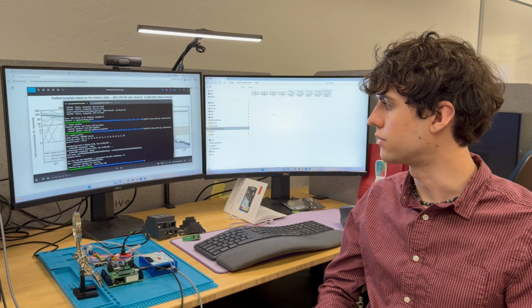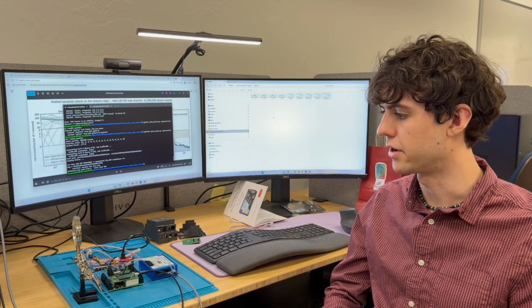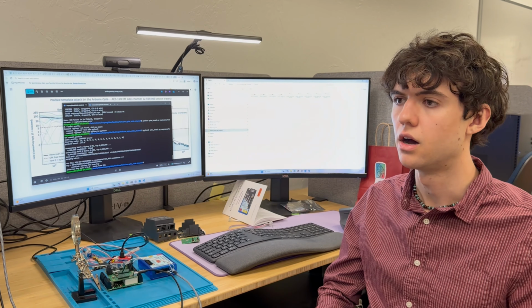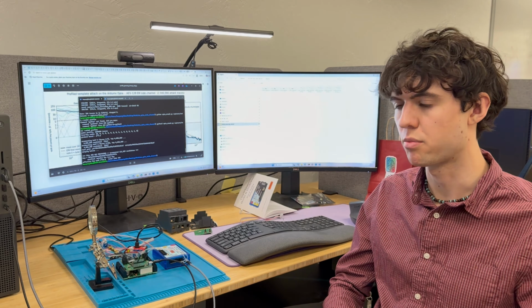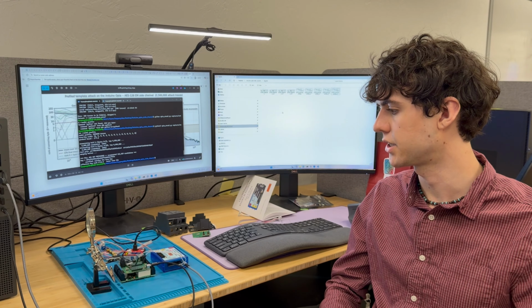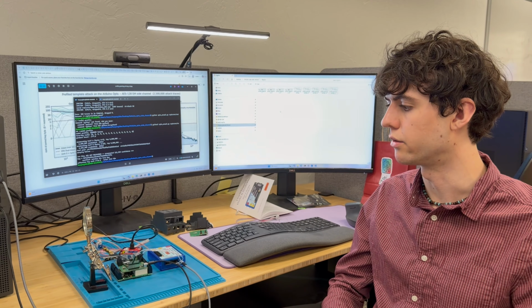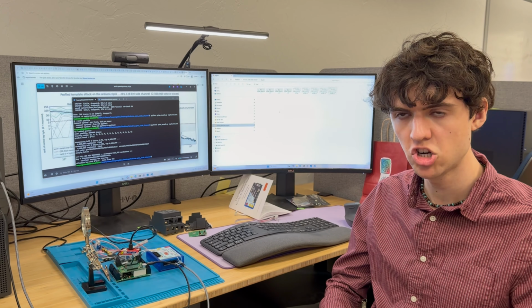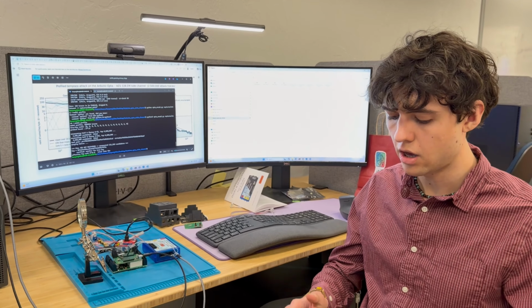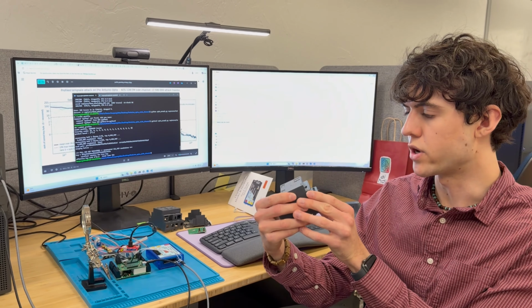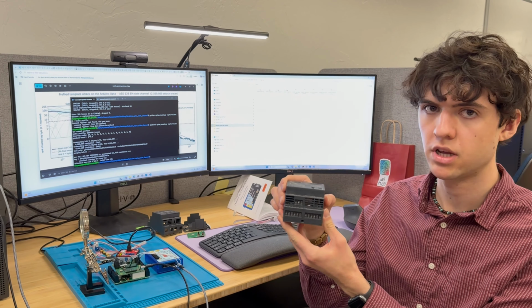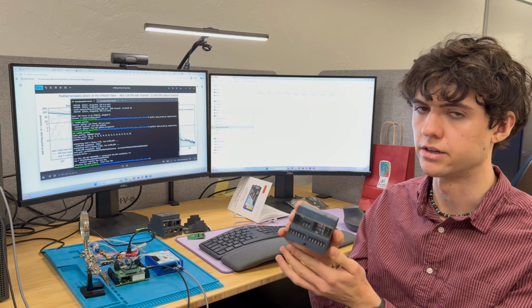So in summary, we've demonstrated AES key recovery from the microcontroller unit on this PLC. Since PLCs are commonly employed in important industrial applications, any sort of hardware vulnerability on these can be high stakes. One proposed mitigation we might implement is time randomization, inserting random operations in between the standard AES operations to mask leakage. And for further attack work, this is an assembled PLC. If we get a smaller EM probe, we might be able to insert it and grab leakage off of an assembled PLC.